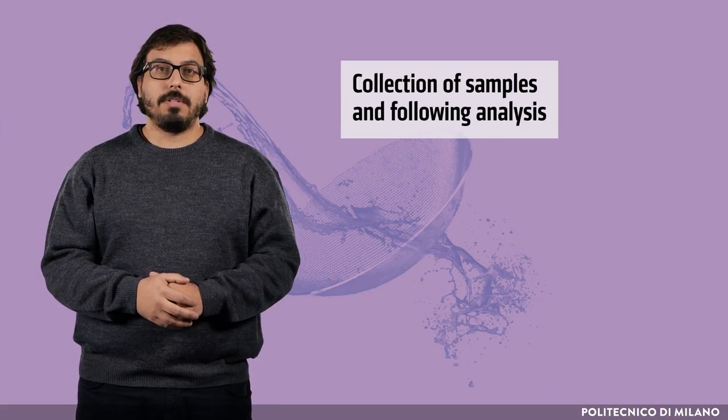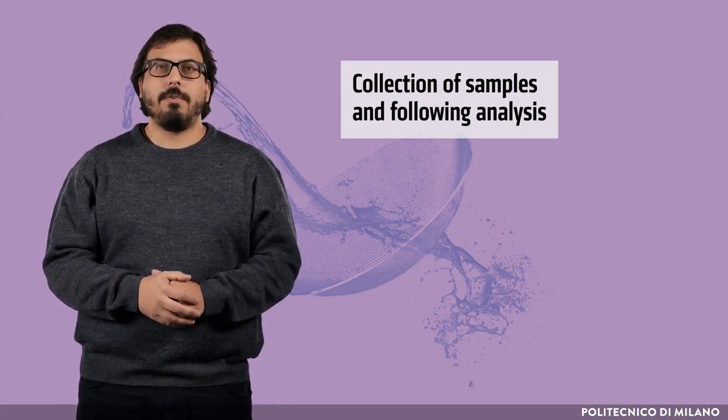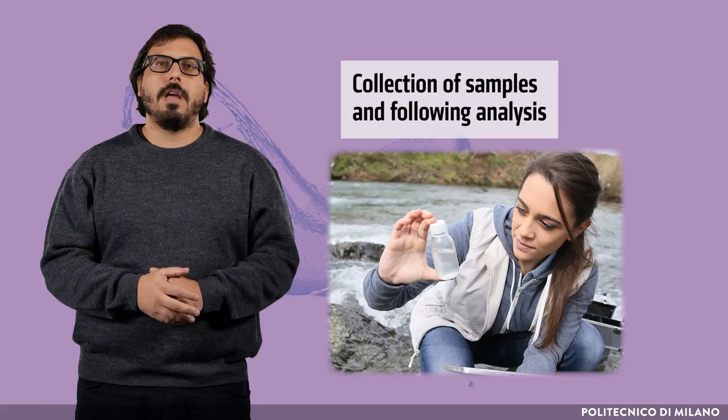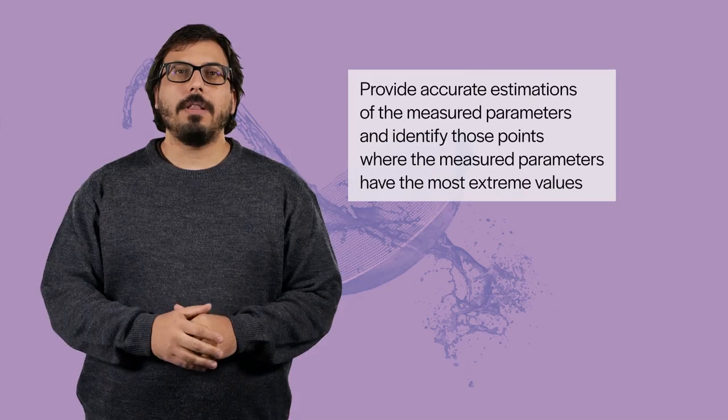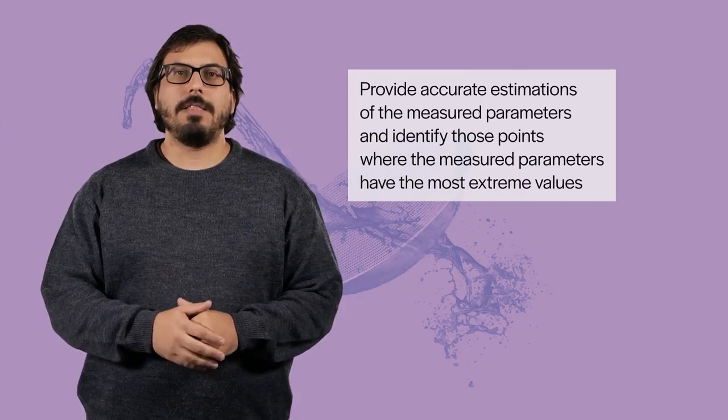Traditionally, the collection process has been performed manually, for instance by a human operator who collects a water sample to be analyzed in a laboratory afterwards. Recently, in a wide range of settings, the manual approach has been substituted with online analyzers, which automatically collect samples at fixed frequency and use specific sensors that automatically communicate the measured value of the analyzed parameter to an external processing unit.